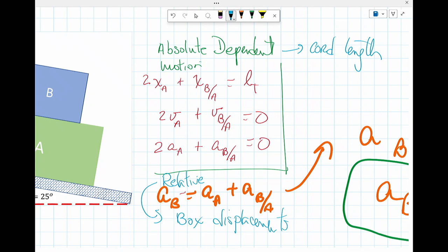But when you do relative velocities between two objects, one sitting on top of another, you have the velocity of the bottom object and the velocity of the top object. And so when you look at the top object, it's the velocity of the top object relative to the bottom. And that's why I end up now with two seemingly contradictory equations, because these don't make sense, because otherwise AB equals 0 or some form of 0, minus plus AB and all sorts of things. That's not what it is. So if you can separate out both of those, then you can solve for the kinematics. And it's important to be able to do this.